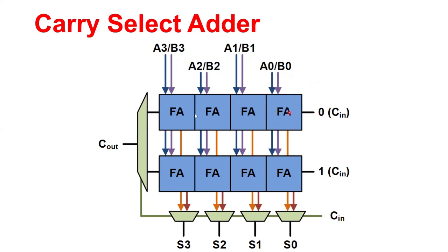It could be 4-bit, 8-bit, 16-bit, and it is efficient, with less power and less area because there is a smaller number of logic gates inside this architectural block. But the problem here is that the carry generated from the previous stage goes to the next stage. That's how we call it a carry ripple. And the sum, the orange line, has to wait before the carry propagates from the previous stage to the next stage, and that makes it a slower architecture.